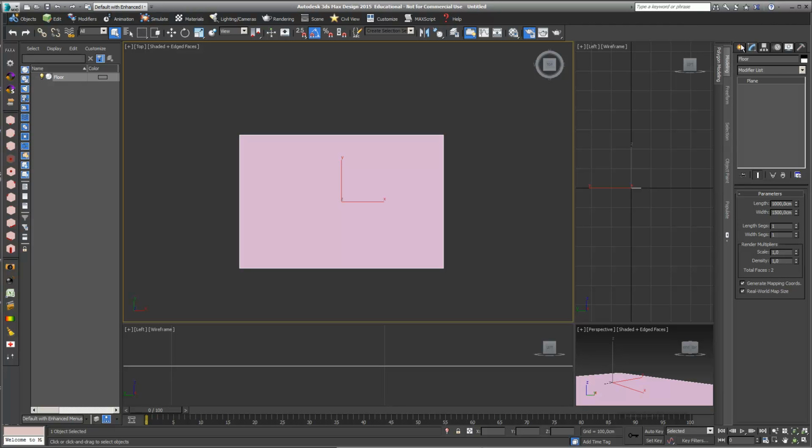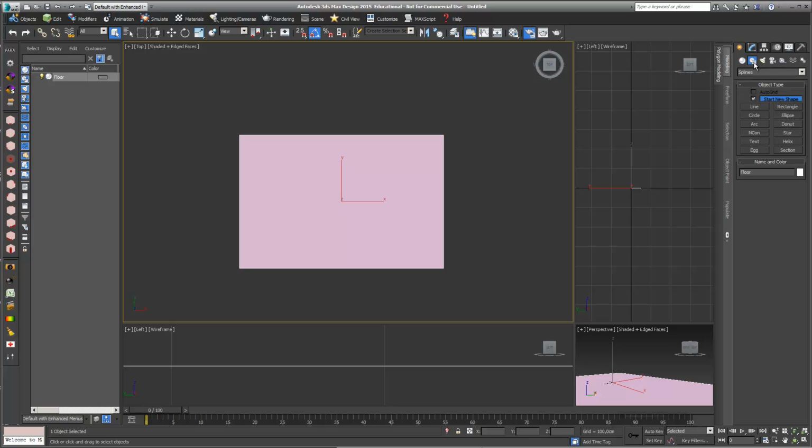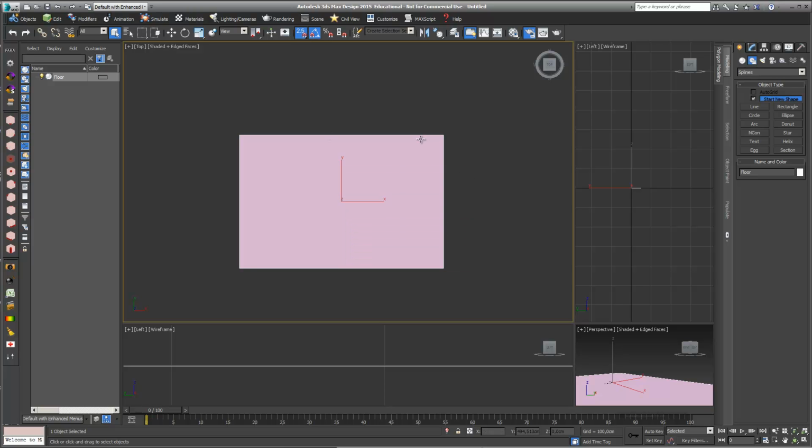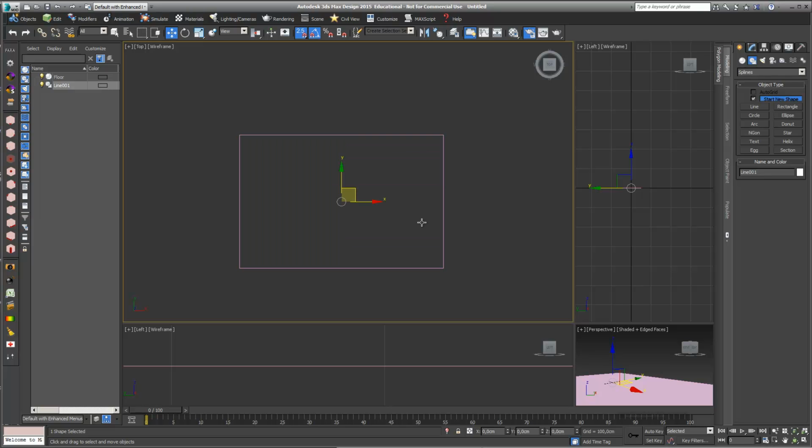And next step, I just draw a simple line for actually the walls. I just go into my S snap functions, right mouse click vertex, and I redraw this. And I just go into line, and I just press my first point, a second point, I just snap my points like this, and it's probably like this, that this space is not really complex enough.